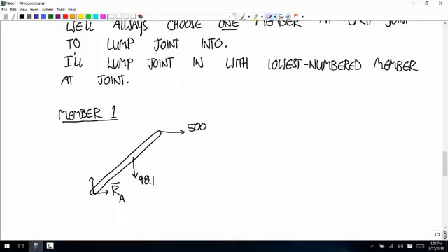And then there's one more. So if you go around the boundary looking for where the surroundings make contact with the boundary, there's one more contact that we haven't put in there yet. Yeah, there is the force that member 2 is applying to the pin, which is part of member 1. It's a pin joint, so that's an unknown force vector. And I'm going to call that the force on 1 by 2.